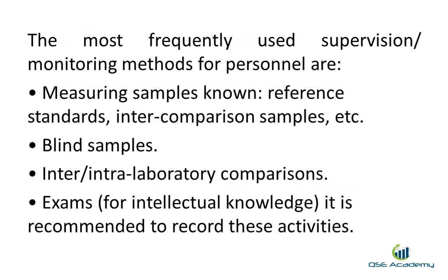The most frequently used supervision and monitoring methods for personnel are measuring samples with known values, reference standards, inter-comparison samples, blind samples, intra-laboratory comparisons, and exams for intellectual knowledge. It is recommended to record these activities.